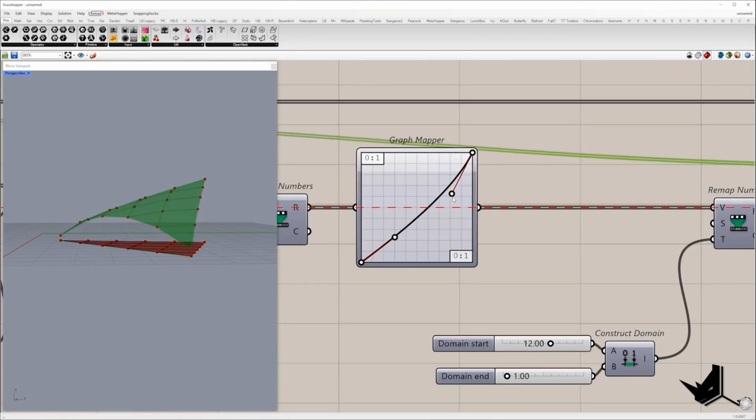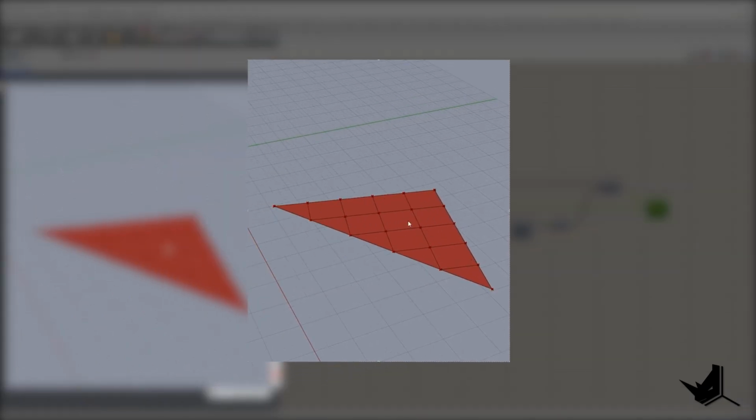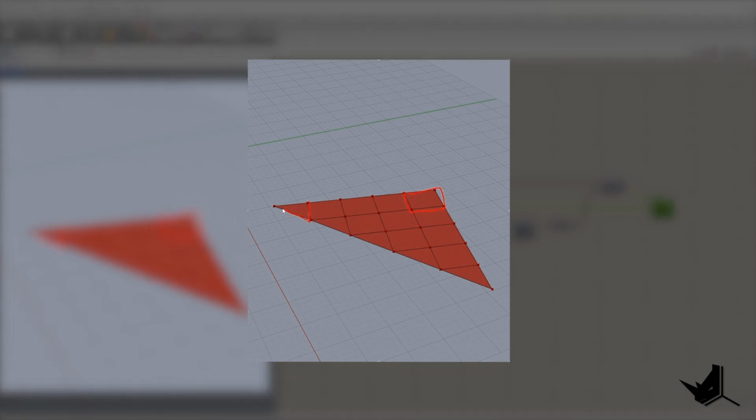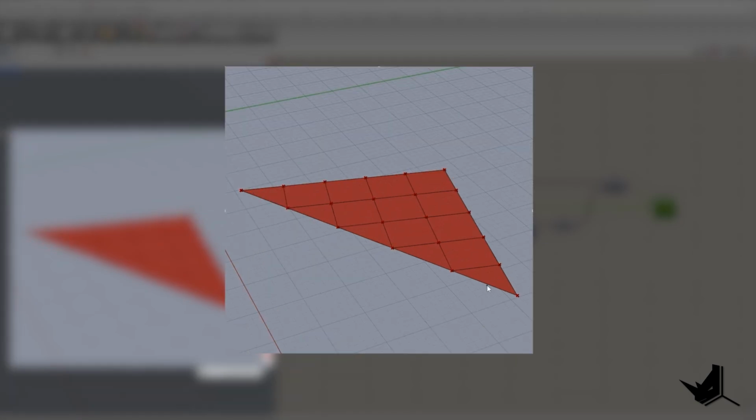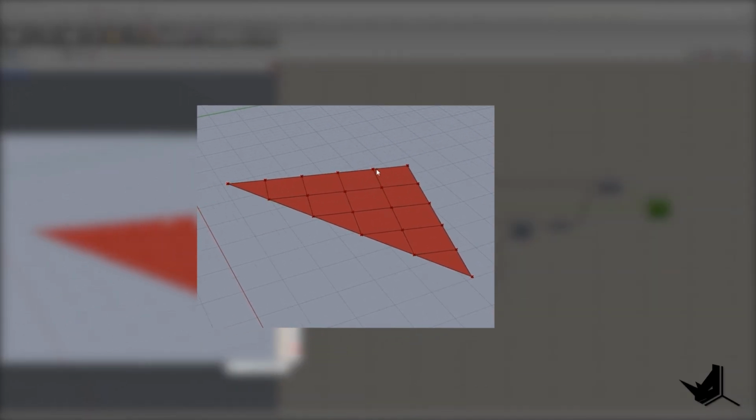Basically, you can see here how we can adjust these points. We need to take our initial curves and explode them. So inside each branch we'll have segments of elements, either triangles or squares. And these segments we need to sort based on distance from the attractor point to the middle point of each segment. Once we sort these segments, inside one list will be the first 2 items.